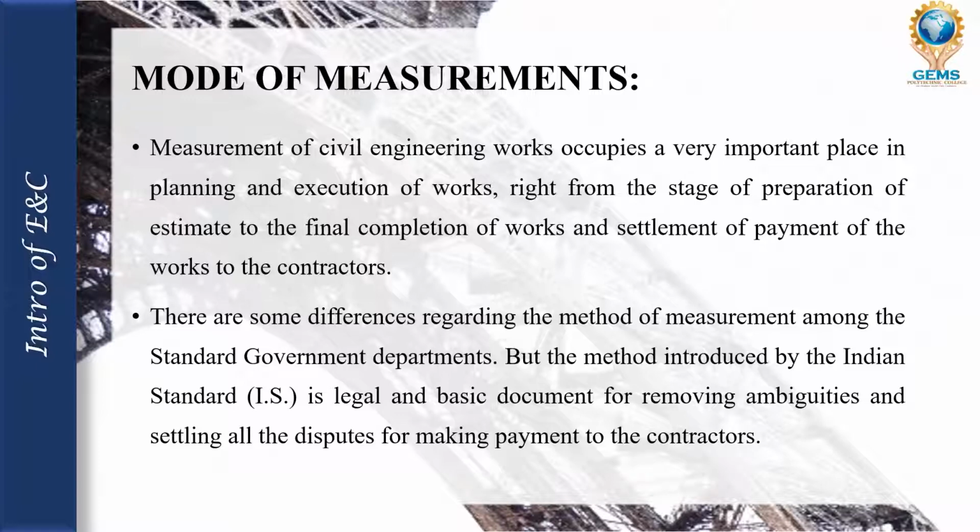Then what are the units of measurement? For example, for earthwork we have meter cube as unit. Then for RCC work, meter cube. Then for DPC, meter square. For flooring we use meter square. So everything, okay, everything has a measurement, right? So that unit of measurement we are going to study in this unit.